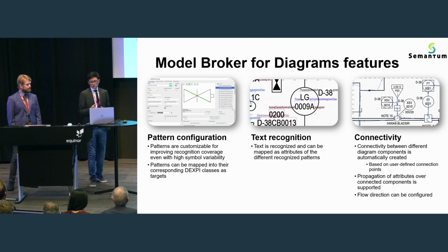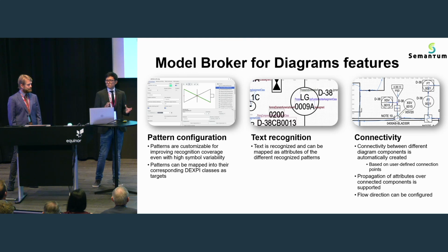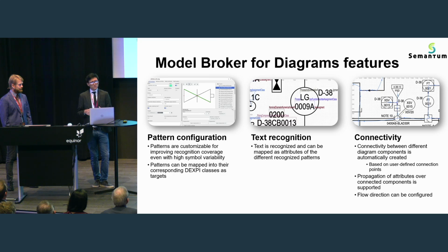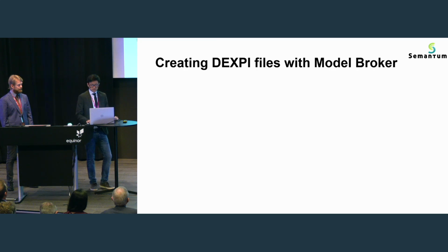As you see there, we have this text recognition. Using regular expressions, we can take the text that we are finding and map it into corresponding attributes. And then by configuring terminals, we are also able to create connectivity automatically in these diagrams.